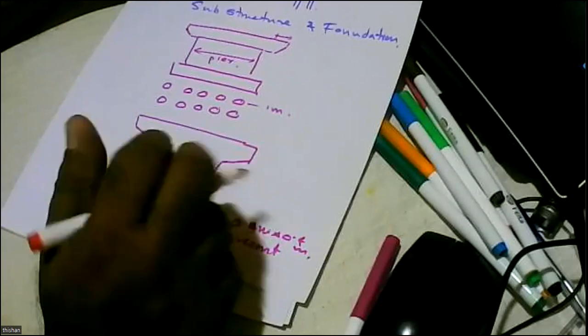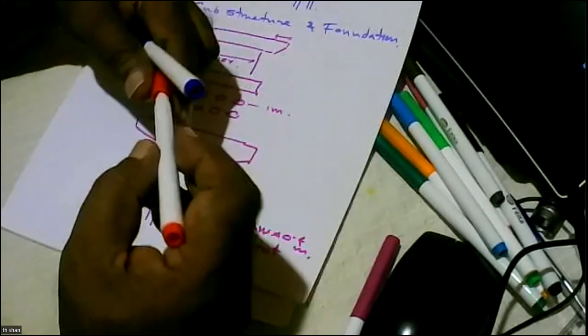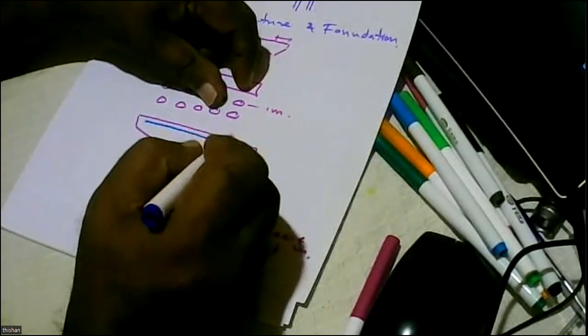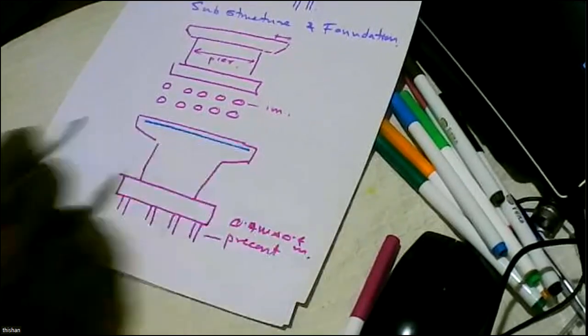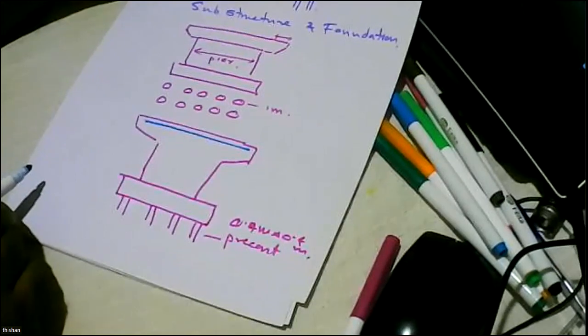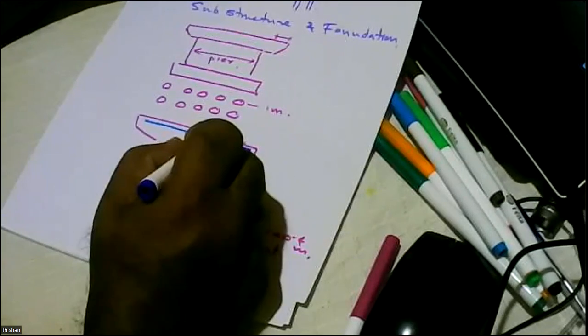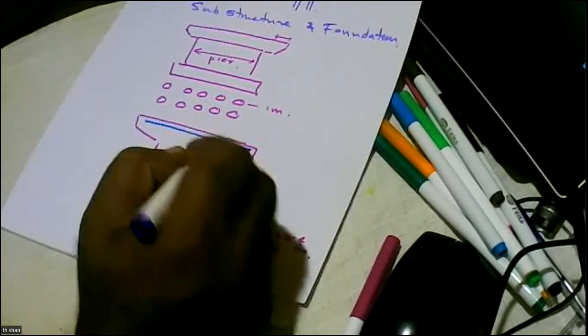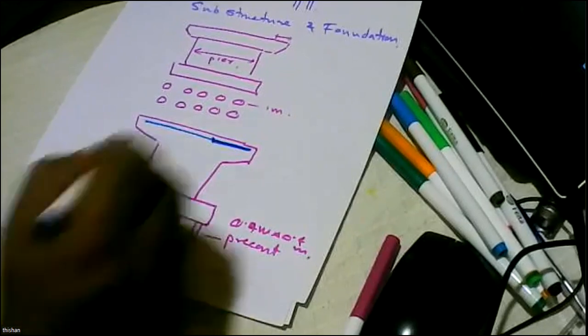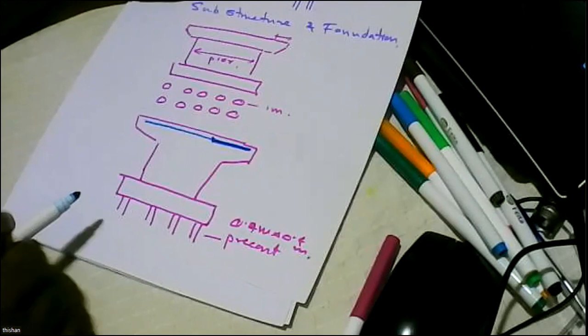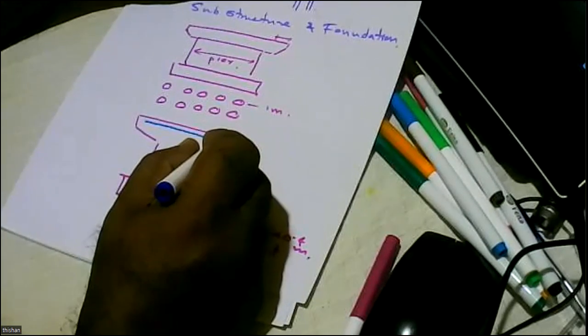Now, what happened in Southern Highway was there was a little dispute between the designers and the consultants. In this cantilever part, most of the reinforcement was curtailed at a particular section. If you look at Eurocodes and all the codes, we are generally discouraged from curtailing a lot of bars at one section because there can be stress concentrations.